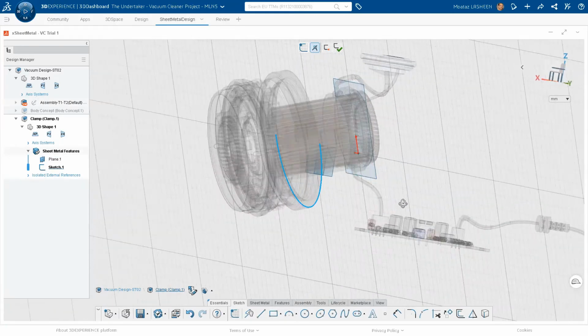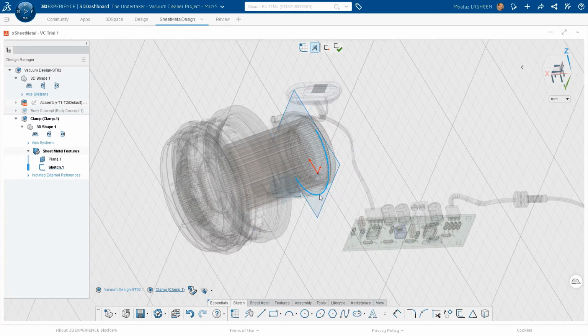the plane on the edge and using even the edge, convert to entities, and then use that resultant circle to create my sketch. I don't need the whole circle, so I will trim the unwanted piece of the circle to keep only the arc. And then I always keep my design intent by adding dimensions. So I will add a dimension here.